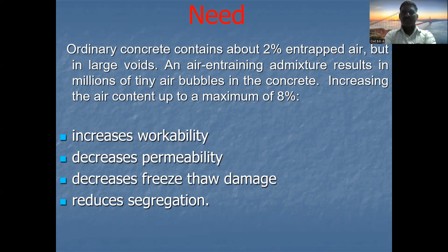But now only that is not sufficient. Why? Because depending upon the environmental condition, we may require early setting of concrete. We have to provide concrete in underwater construction. We have to delay the time of setting. So various factors are there. For those factors we have to add admixtures, and those admixtures play very important roles. Some of the admixtures reduce the water.